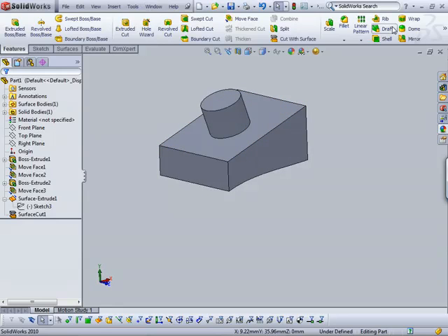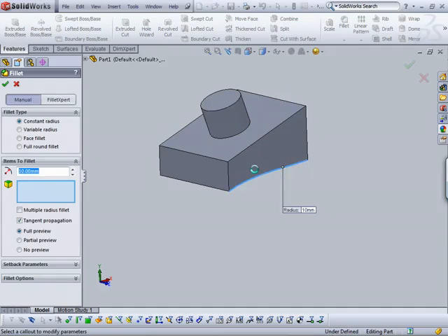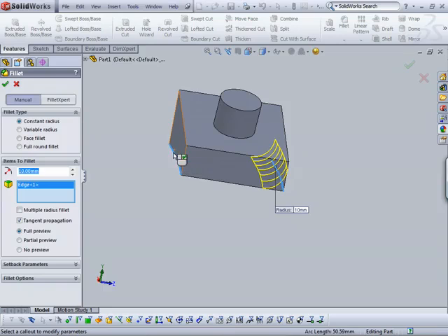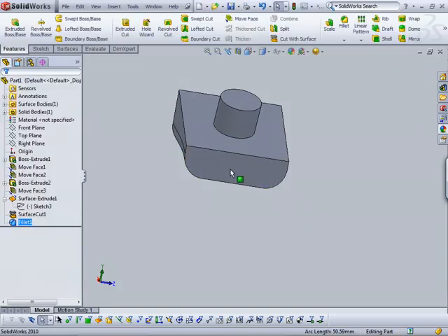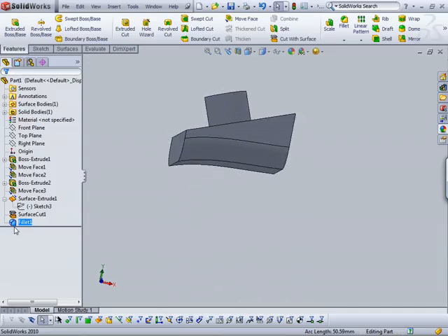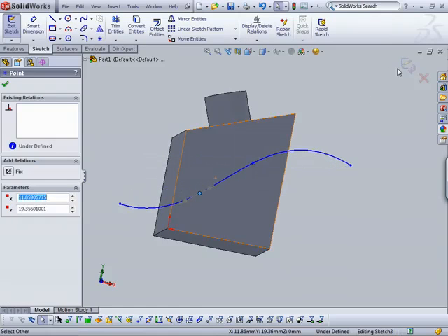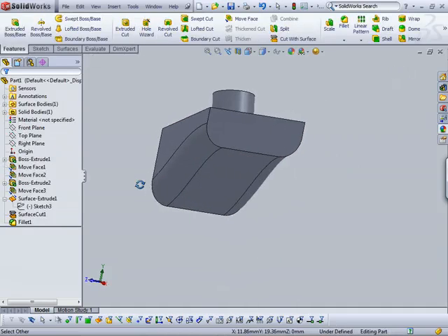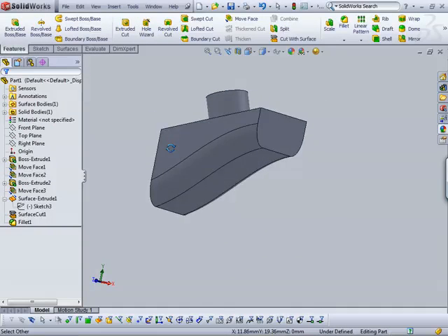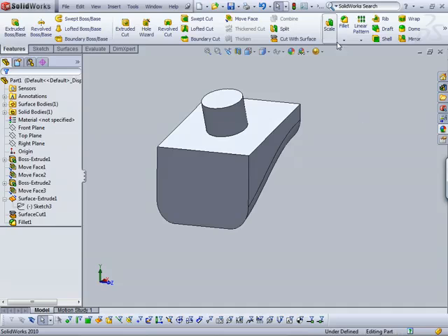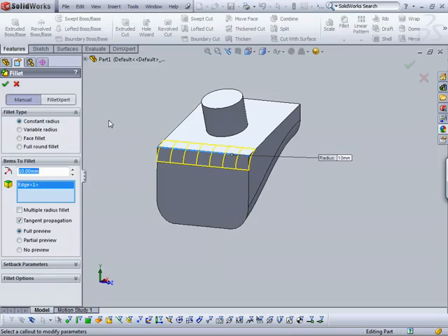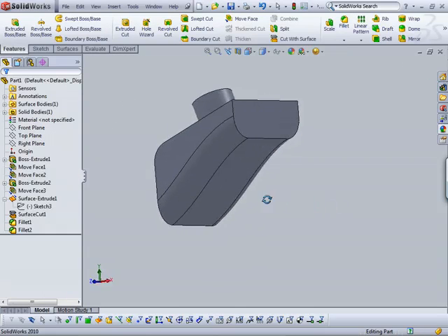And the beauty of that is I can add as many fillets or whatever I want as I like. I can do anything to this model, literally anything, and then go back and make a change to my original sketch, and everything will update perfectly. Okay? Big deal. This is why we like parametric modeling in tools like SolidWorks.